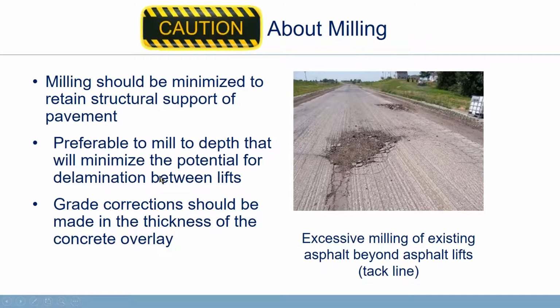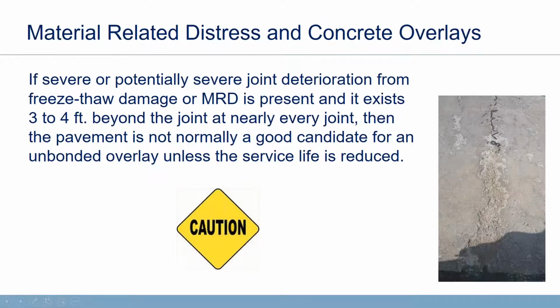It's preferable to mill to a depth that will minimize that potential. And you do sometimes need to make some grade corrections, and we understand that, but again, make sure that you know how much thickness you've got down there in that pavement.